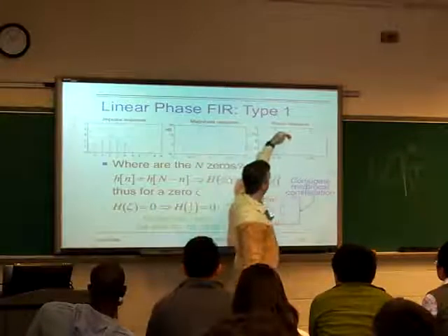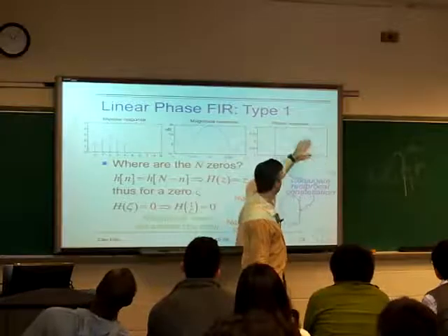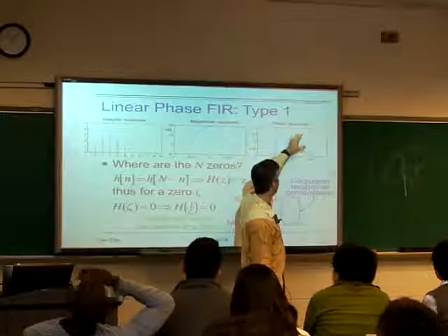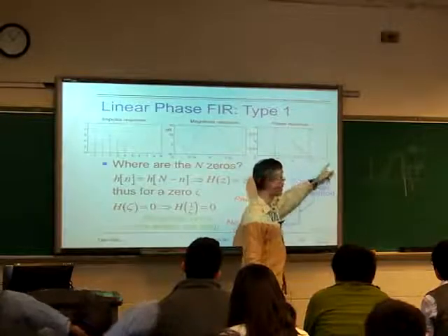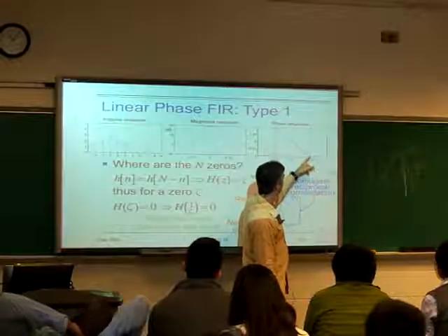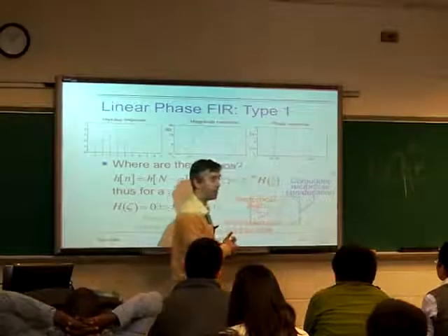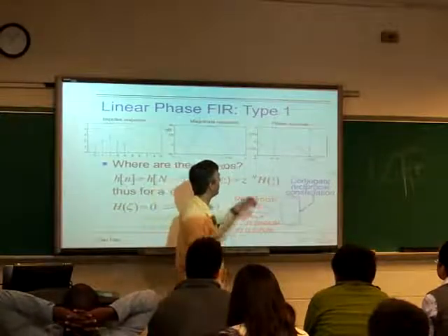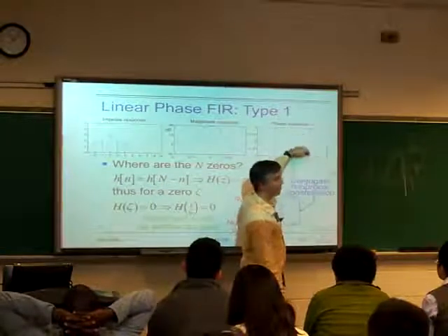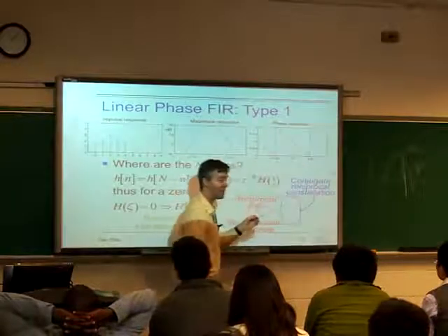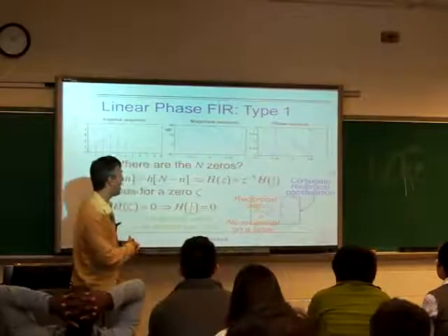Of course, the linear phase function, which has got a slope of minus 2, will wrap around. We have the principal values between minus pi and pi. So here it wants to go from 0 to minus 2 pi for omega equals 0 to pi, but at omega equals 0.5 pi, it wraps around and comes back up the top. But that's just the 2 pi ambiguity in the phase function. So again, we'll see a lot of phase functions that look like this. They're straight with these jumps in, but the important part is the straight part, saying that the slope is locally constant. The slope is constant for all frequencies, apart from the discontinuities.